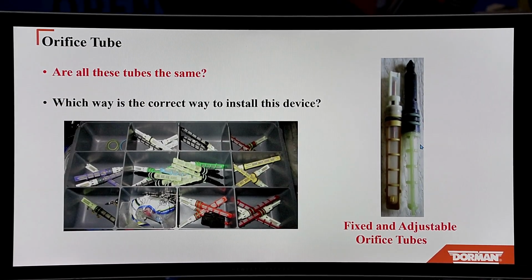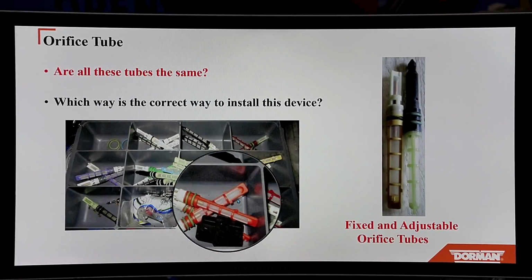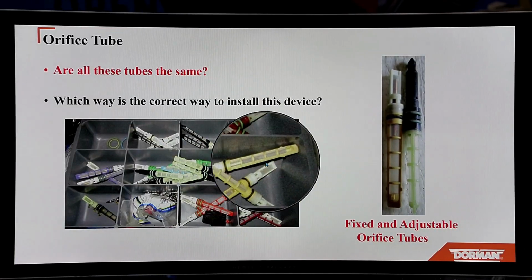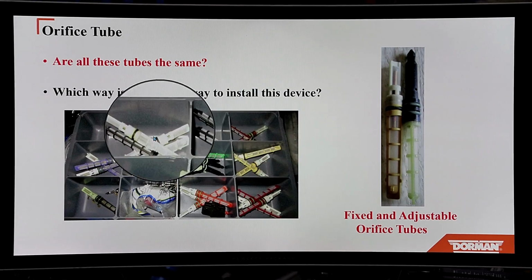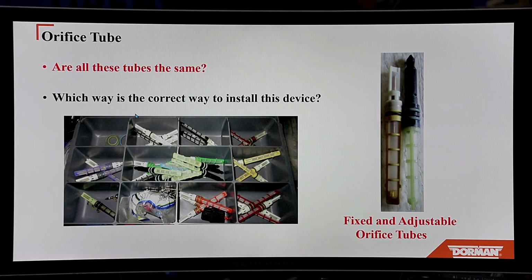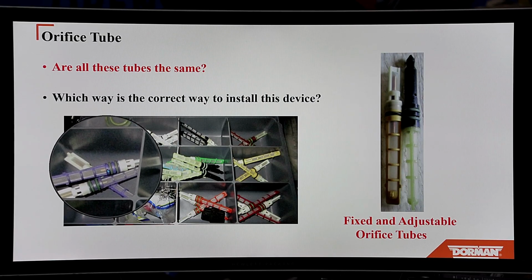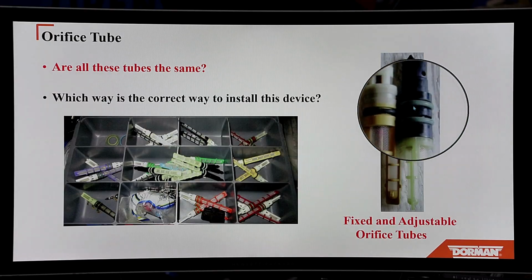Now, if it doesn't have that, it has an orifice tube. There's all different color orifice tubes, not to make you happy. You know, yellow, Mr. Smiley Face, green, you're a tree hugger, right? You know, black or white, hey, a black and white cookie, all good, right? But guess what? They're all different orifices. They're fixed orifice.